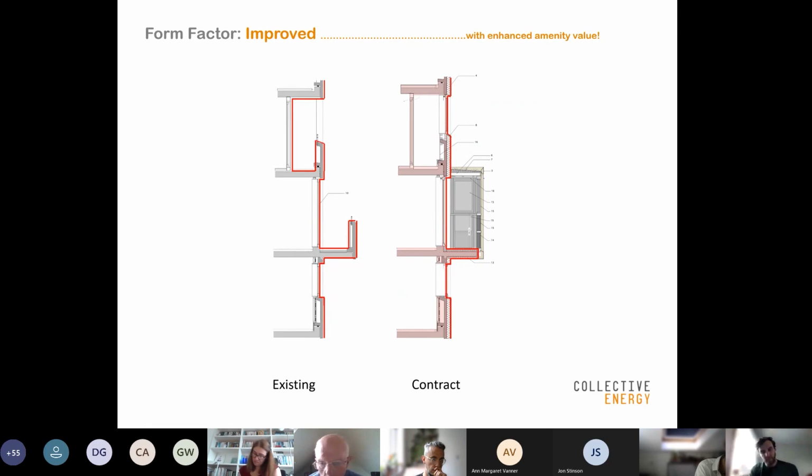We had historically recessed balconies on approximately half of the flat types and projecting amenity balconies on the other half. By bringing the recessed balconies within the thermal envelope and taking the triple glazing to the outside of that balcony, we reduced down the thermal envelope by around 20%, which was quite considerable considering the size of the buildings. The projecting amenity balconies were an inherent thermal bridge.